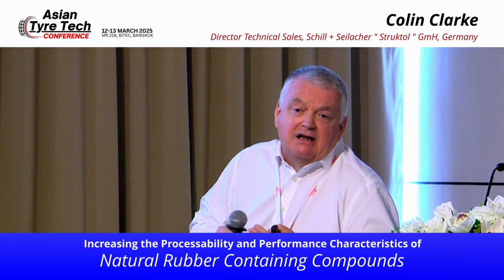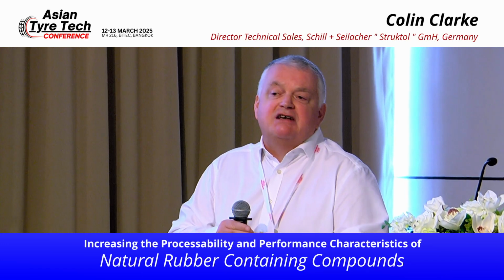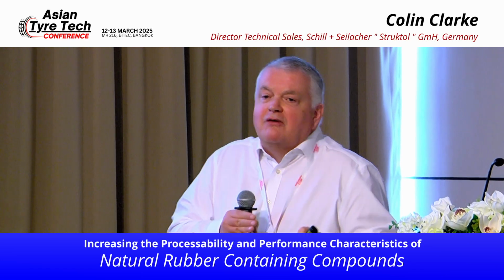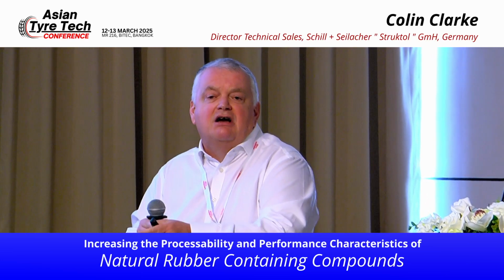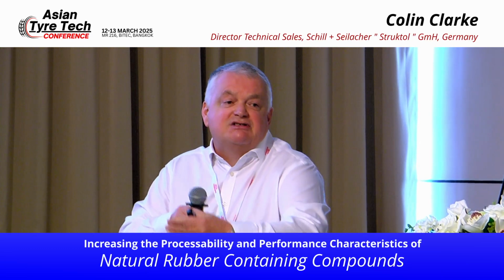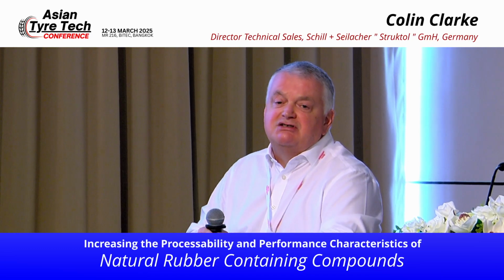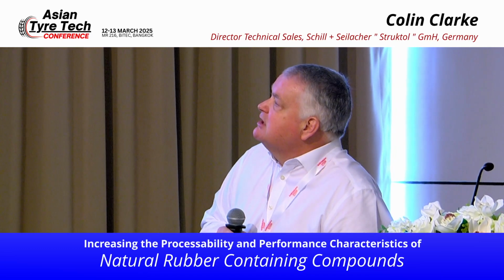Of course, then we want to balance that against good dynamic properties. In the first study, we looked at a very high severity test, the blowout test, with the flexometer. But actually, we don't really want to fail those compounds. So one other way to measure that is to just look at the tan delta, the hysteresis at 60 degrees centigrade. Any reduction in tan delta means a lower hysteresis. It means an energy-saving component, so we have less heat build-up in that component.